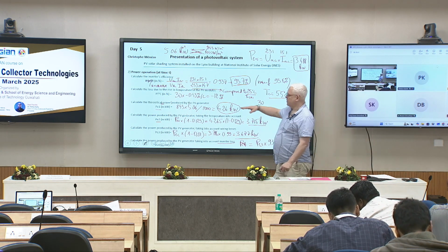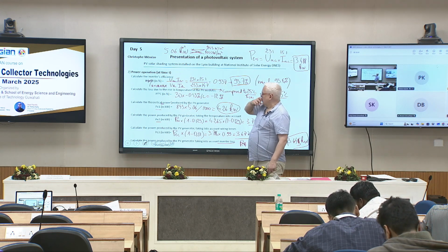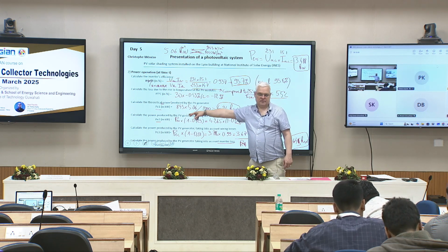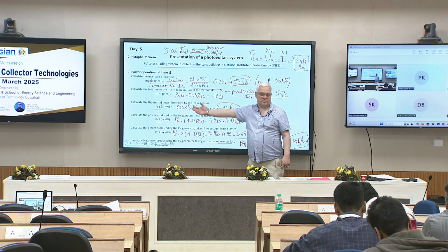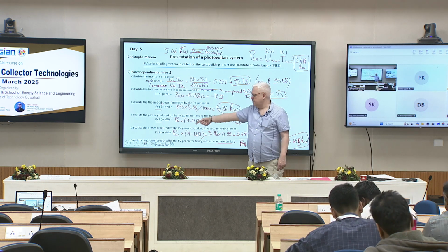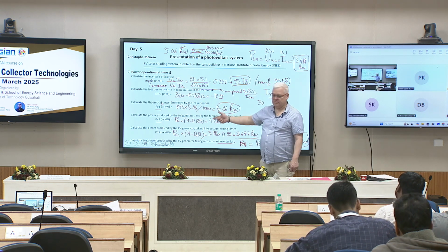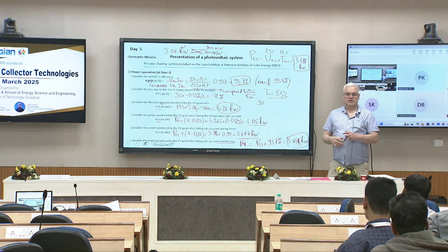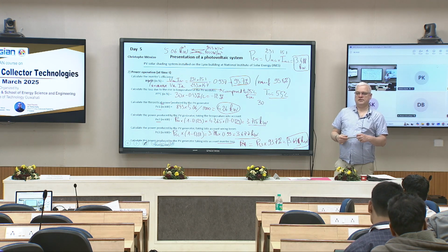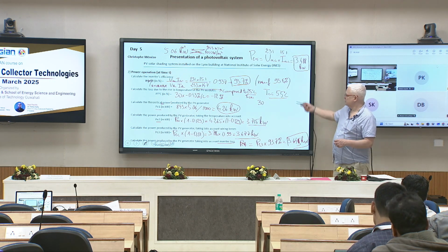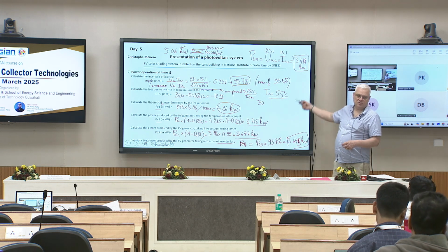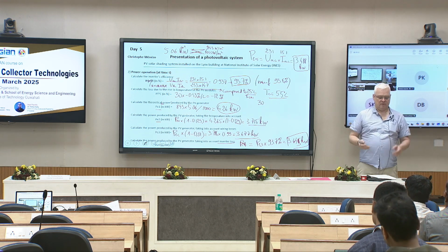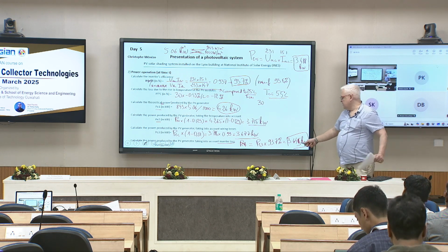The fact that we have not 1000 radiation but 843, so the power is lower, is not a problem. It's consistent. We consider the temperature and the power is low, it's consistent. Okay. The cable that we estimate at 1% in loss, this is a way to check that the assumption is not so bad. Okay, the cable seems to be okay. We are not far.